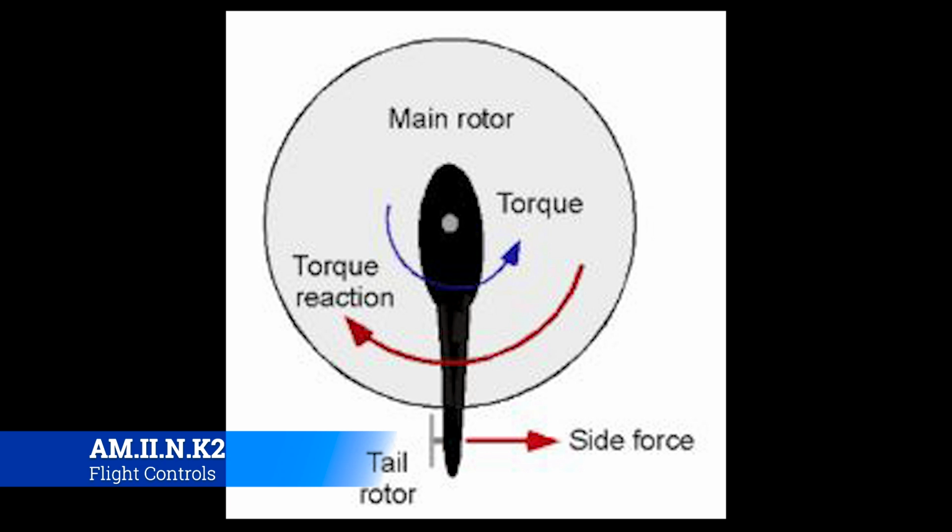On a helicopter, it's even more complicated, because let's say you want to climb and you pull collective and you increase pitch, that extra load on the rotor disc slows the rotor disc going around. It's real simple. If I told you to run 100 meters, you would run it. Now if I gave you a baby hippopotamus and told you to run with it 100 meters, you would run a lot slower because there's a lot more weight in your arms. This is no different. If you pull pitch, the rotor has to move that much more air because of the increased angle of attack on the rotor disc, and it slows the rotor from spinning around.